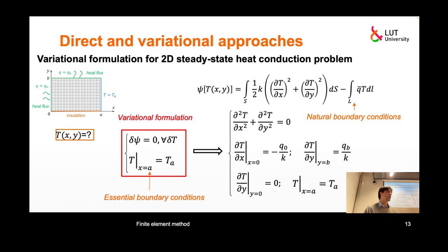So natural default boundary conditions would be, in this problem, natural boundary conditions with 0 heat flux. So this insulation on this bottom line here means 0 heat flux across that boundary, and that will be kind of default boundary conditions if you're using commercial codes based on this variational formulation. Okay, but it will be more clear when we do it ourselves with coding.